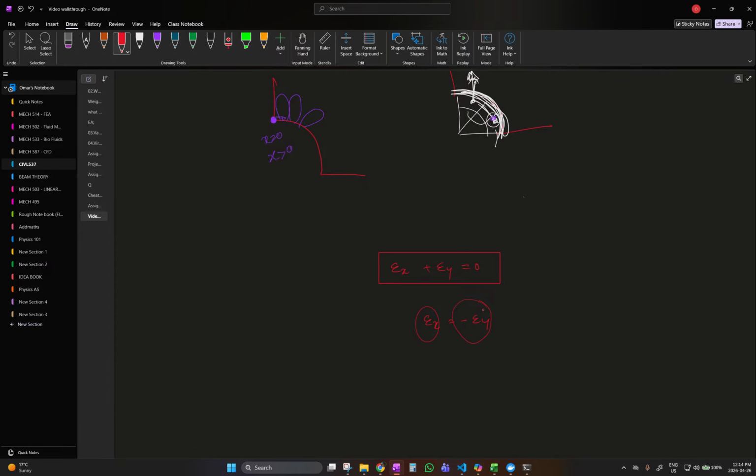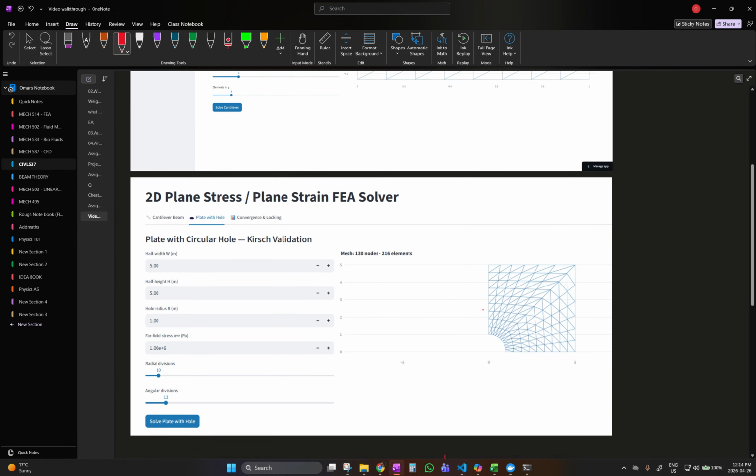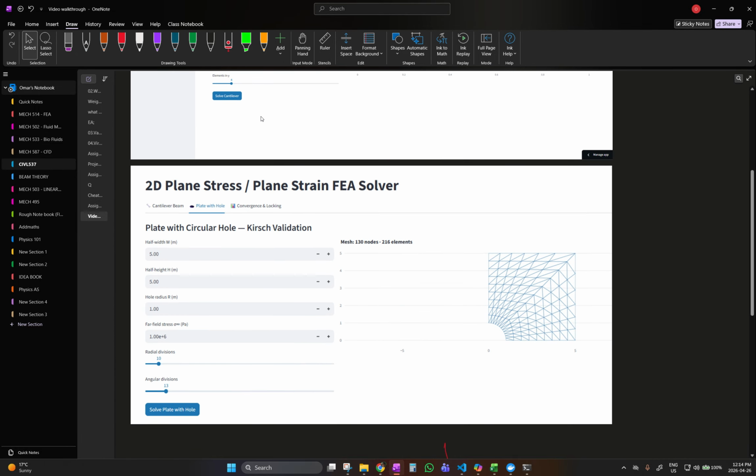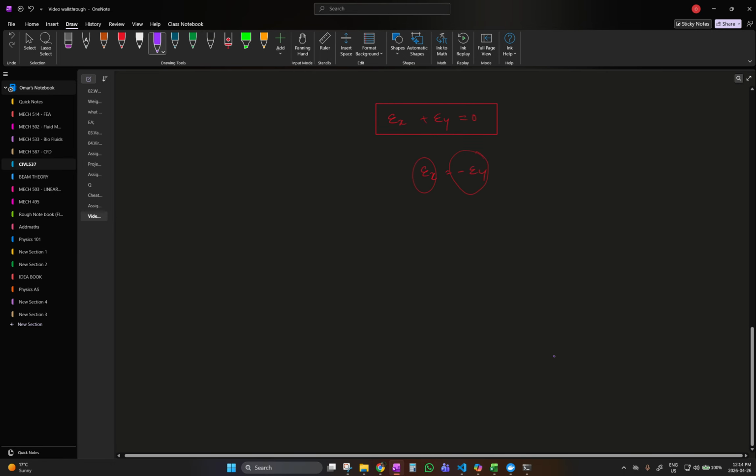But look at the nodal constraints over here. If I am applying a load over here, this will result in some strain, and this strain must match the strain in this direction negatively. But these nodes are fixed. So essentially, this condition cannot work. So it becomes really, really stiff. This is what happens physically.